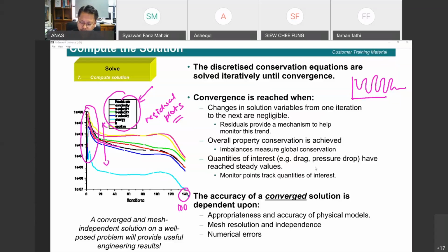Okay, for example, if we have a domain over here, and we have an inlet over here and an outlet. Remember when I said usually we have V for the inlet and we have P, or pressure, at the outlet, because we do not want to specify the V at the outlet, since we want to check the flow or the outflow happening. Here we want to check the velocity going out.